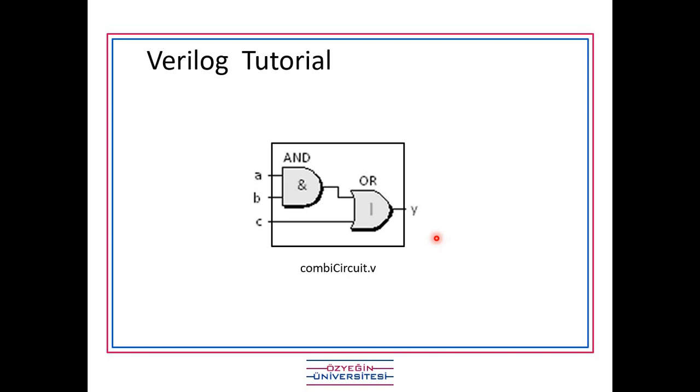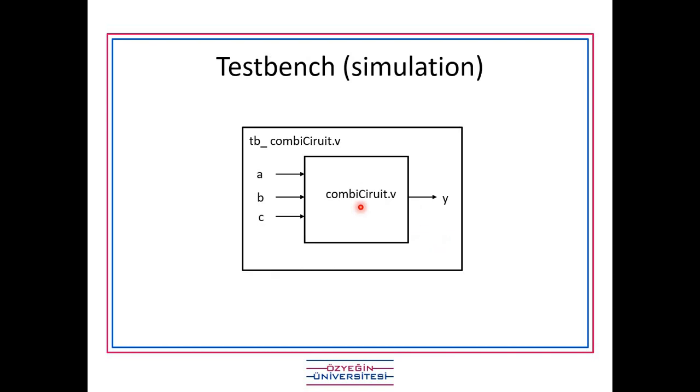After we have designed our design, we have to simulate it. We need simulation because we have to check if our module, if our circuit is working correctly or not before loading it into the FPGA. Because we are doing this online, we don't load it, but normally in the design flow, when you design your circuit, you then pass it through a test bench. You have to give it inputs and expect outputs. If you don't get the expected output, then the design has to be revised again. And that's the way to go.